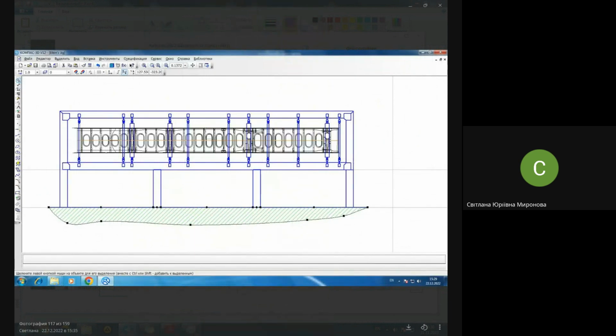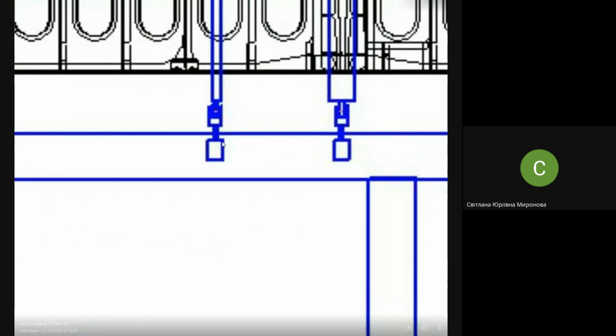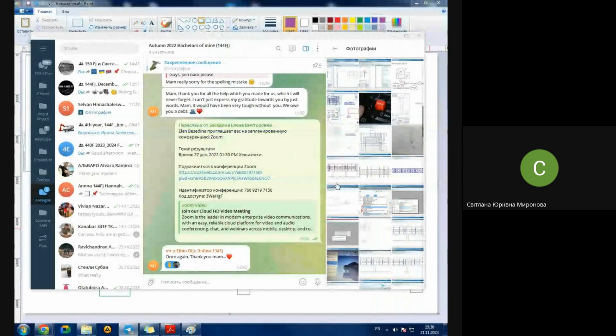No, it's a scheme also. It's not a drawing. What is the difference between just a scheme and an assembly drawing? In a scheme it's shown like, okay, it's a fork, it's a barrel, and that is a contour locator. In a drawing, everything must be detailed. It must show exactly all the assembly places, all the places where you have joints. They should be shown in cross-sections, they should be detailed so that the one who mounts and assembles the jig might understand what it looks like.